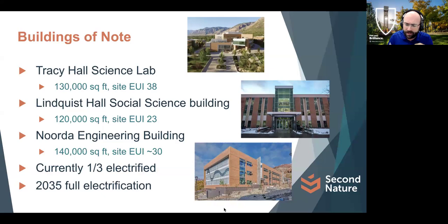I think I neglected to mention our approach. Both Michael and Ted mentioned the idea of low temperature hot water. When I say low temperature condenser water, our loop is generally in the 50-degree range, and that's what's being sent to the heat pumps. I did see another question come through the chat about what to do when your heating and cooling loads aren't balanced.